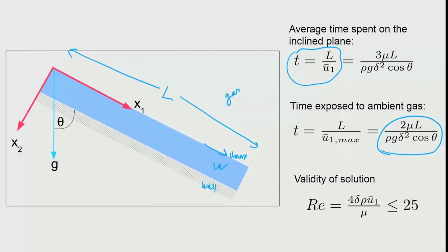So, that is from the Reynolds number. So, we see that the Reynolds number as defined here can then be used to see that it is less than a critical number. So, this is the critical Reynolds number, and here in this problem it turns out to be 25. So, smaller is always better. So, if you ensure that the numbers that you got are within this particular limit 25, then that means that the solution you got is reasonable. So, you could actually use those numbers as meaningful solutions out of the problem that we have.